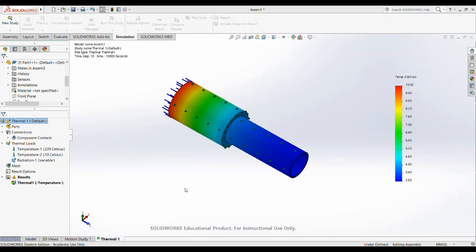So there's different ways of doing this. As I showed you in class, the bond line that I had here, you can see it a little bit, was really thin. So there was very little connection between here and here. You can see this one is starting to get isothermal. This is kind of uniform temperature, because remember I changed the material to steel.